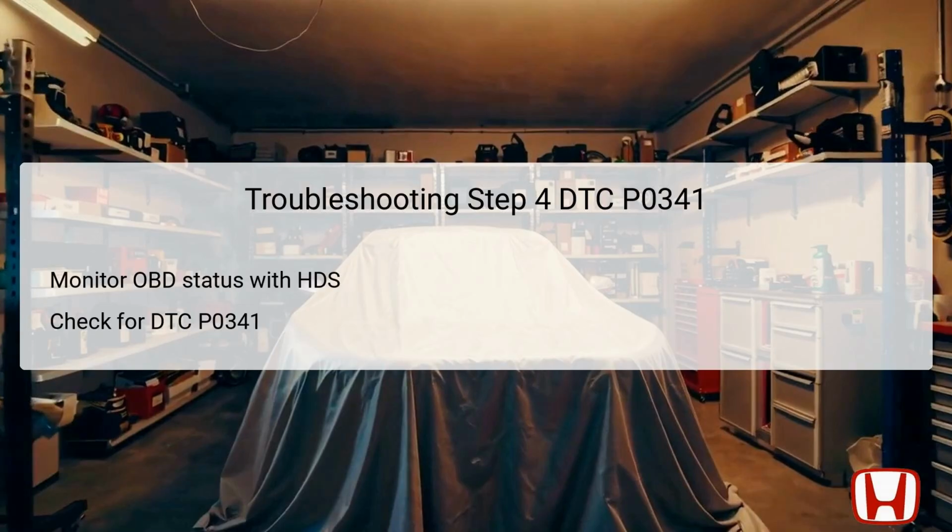In Step 4, monitoring the onboard diagnostic (OBD) status is crucial to ascertain if the issue persists. Use the HDS to observe the DTCs listed in the menu, specifically focusing on P0341. If the HDS indicates that DTC P0341 is flagged as failed, it's essential to go to Step 5 for further diagnostics.